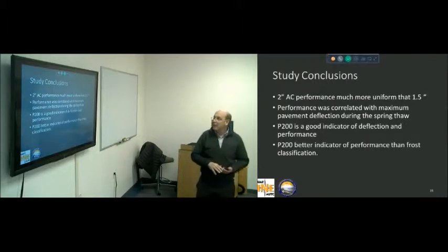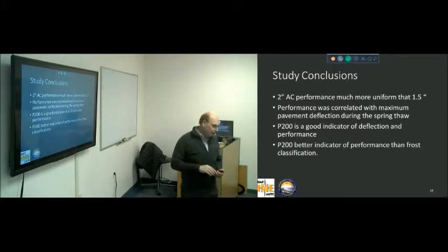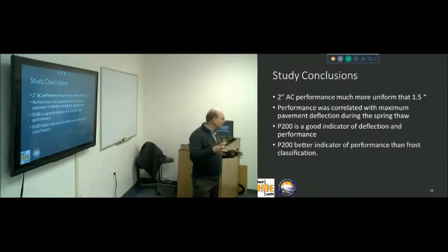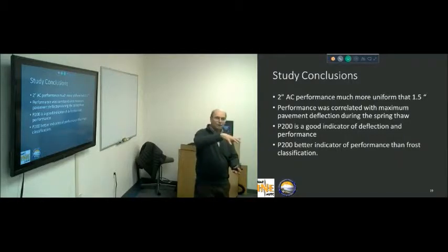Low, much better. But the other thing that did surprise us, for those who may remember the old frost heave test, and we still do that occasionally, we would put a sample in the freezer and allow the bottom to stay warm and the top to stay cold, and we would actually cause the soil to heave.